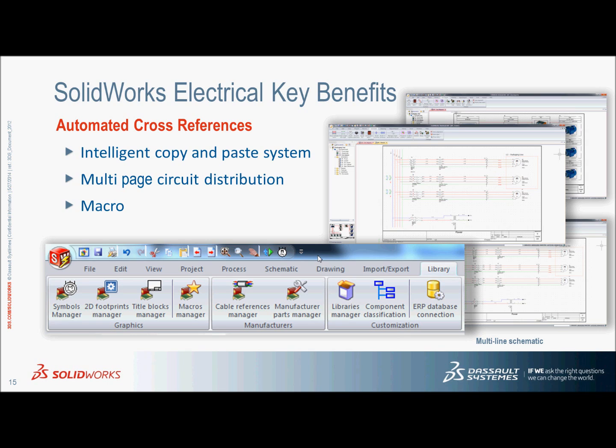In SolidWorks Electrical, copy and paste come with an intelligent system which generates component running numbers by itself, which are also editable when required. The running number is not purely restricted to the current working diagram, but applies throughout the whole project.